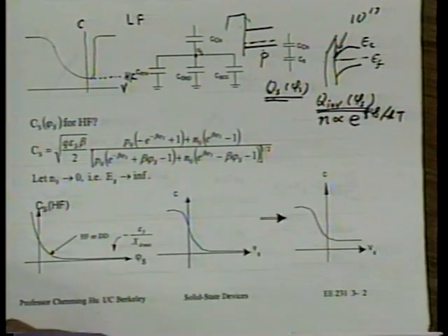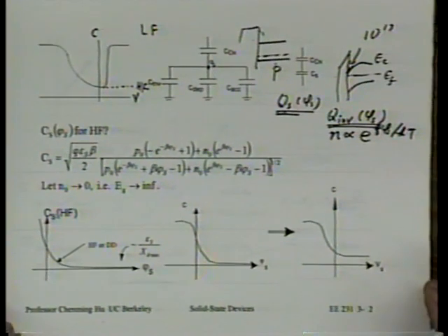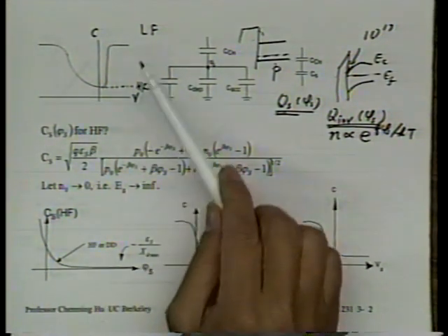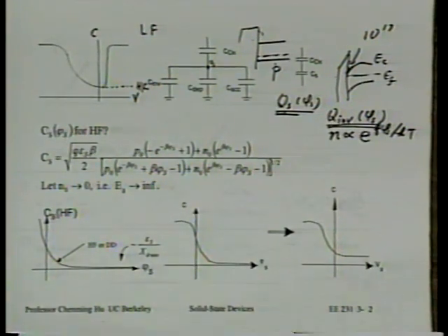All right. So in this sense, then, low frequency capacitance is the more quote-unquote normal, perhaps. Doesn't mean it's more prevalent, all right? But it's the simpler of the two CV curves, because we just assume everything is in equilibrium. The high frequency requires us to consider that electrons don't respond to varying QS, then we have high frequency. That's good. That's the qualitative discussion. Any questions about that?